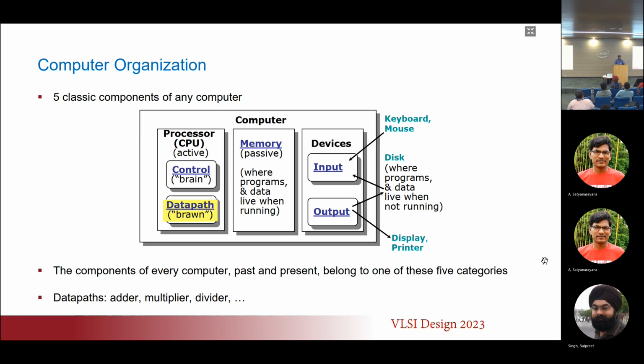The data is passed from the memory to the TPU, so the first part of the process involves copying the data from the memory to the TPU's internal memory. The TPU also features its own DRAM, so you copy from the main DRAM to the DRAM in the TPU. Then once the computation is done, you transfer the result back, which is a copy back. Just those two copy operations introduce huge amounts of latency.